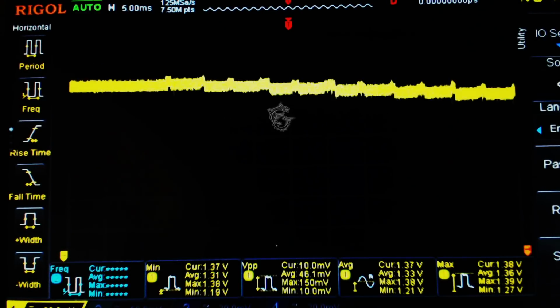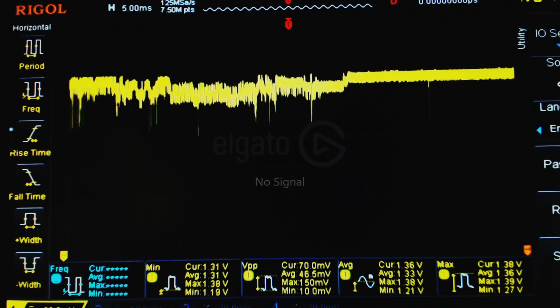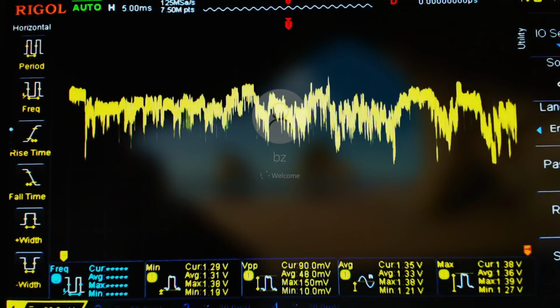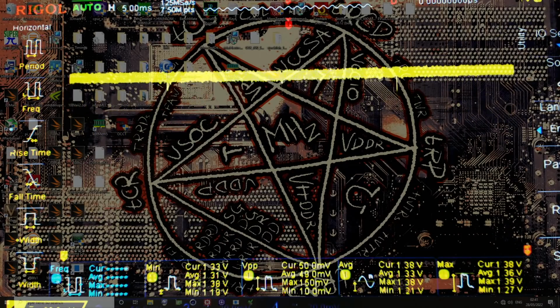And Gigabyte doesn't give you access to switching frequency settings on any of their boards for Z690, and I'm guessing this is why. I'm guessing they tested this and realized that with this chip it wouldn't just be changing the switching frequency anymore; you'd have to redo the control loop of the VRM entirely.